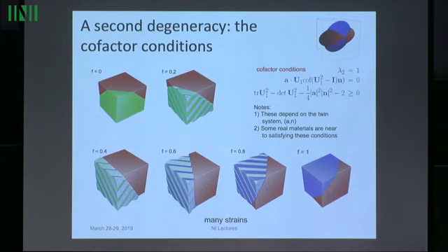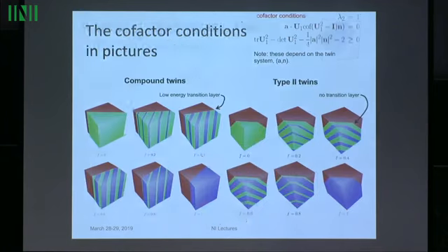But in a way, this should be useful for a transforming material. If you compute the strain ellipsoid as you move along this increasing f, it's going from this strain ellipsoid to this strain ellipsoid. So this is not compatible with this because it doesn't deform when you change the volume fraction. It deforms a lot, but it deforms in such a way that it always has a compatible interface. And now, this is with maybe variants 1 and 2, but if you satisfy this for variants 1 and 2, you've satisfied it for all pairs of variants, okay?